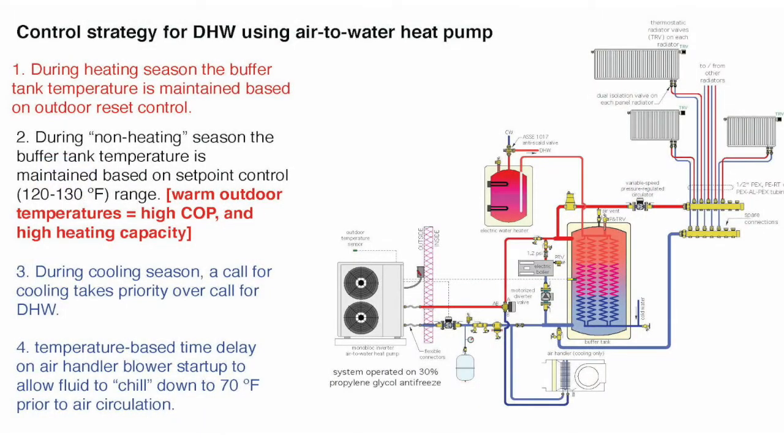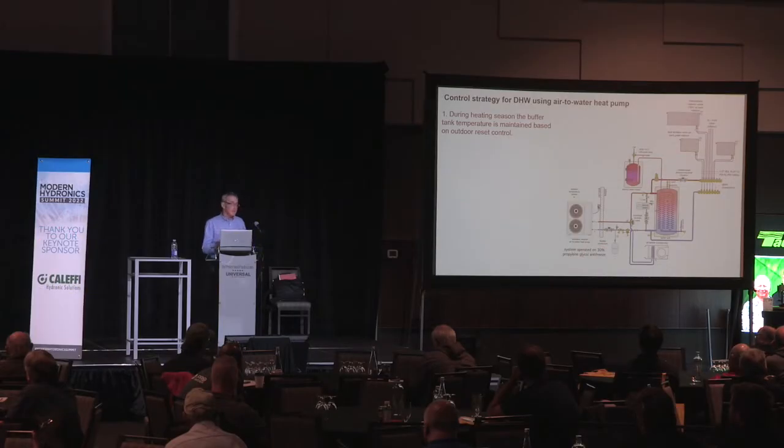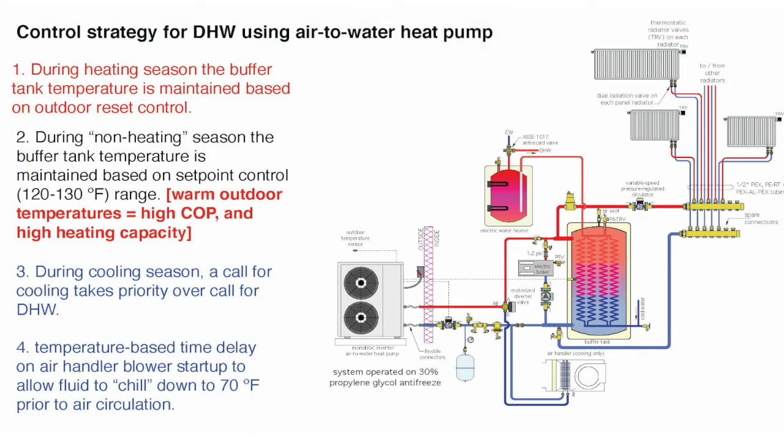And in the heating mode, we're going to send water over to, I'm showing what I refer to as a reverse indirect tank. It's a tank that has water in the shell and then suspended coils. Domestic water goes through the coils, not the shell. So the nice thing about a reverse indirect, it can serve as not only your water heating device, it also can serve as a buffer tank for your space heating loads. And over on the far right, you see I've got a manifold, I've got panel radiators, a variable speed circulator. I think that is an ideal, simple, repeatable, reliable distribution system.